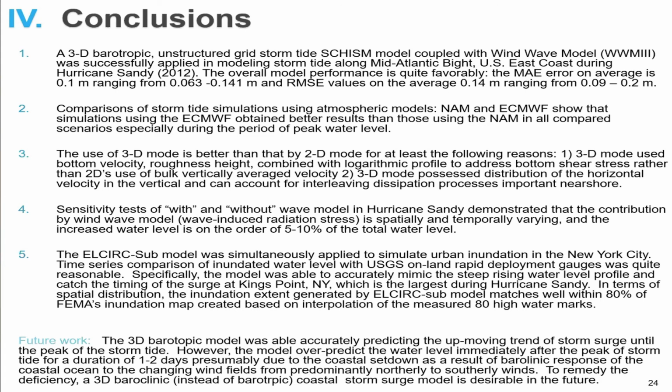In the end, I want to point out the future work. The 3D barotropic model was able to accurately predict the upward trend of the storm surge until the peak of the storm tide. However, the model over-predicts the water level immediately after the peak of the storm tide for a duration of 1 to 2 days, presumably due to the coastal set-down as a result of the baroclinic response of the coastal ocean to the changing wind field from predominantly northerly to southerly wind.